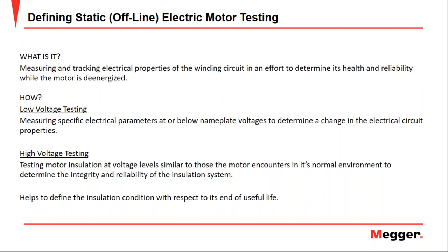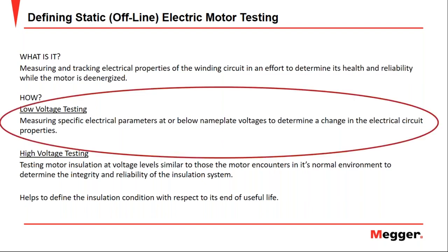The static tests are divided in 2 groups: the low voltage test and the high voltage test. In this webinar, we are going to see the low voltage tests in detail. These tests are performed at or below the bus voltage, never above that level.